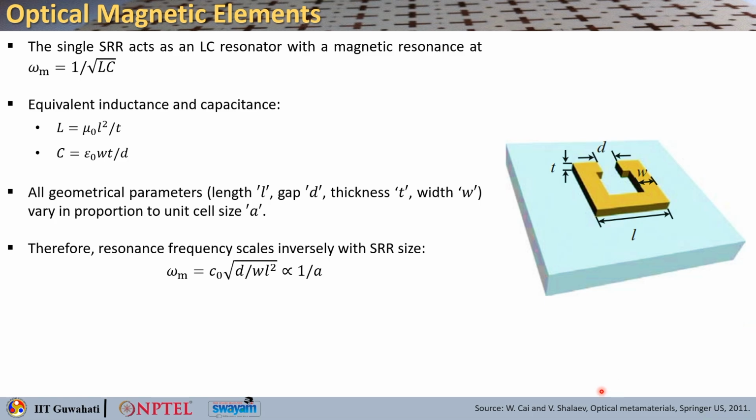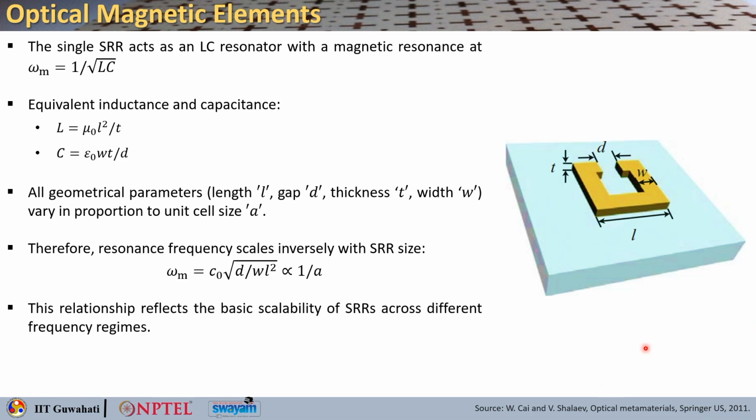Now, this is a very simple expression, and it tells you about the basic scalability of this kind of SRRs across various frequency regimes, and you just need to remember that the resonance frequency is inversely proportional to the size of the unit cell of the SRR, right.